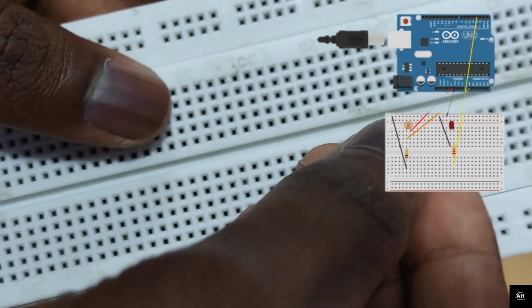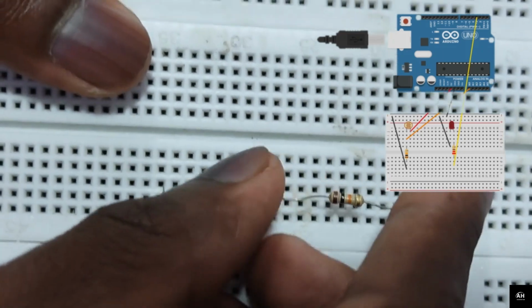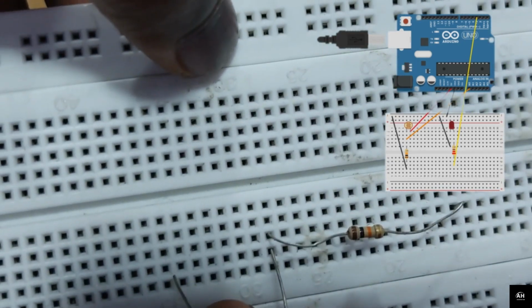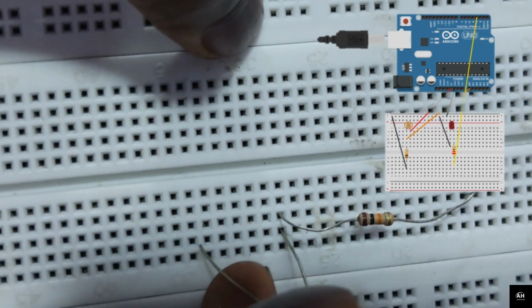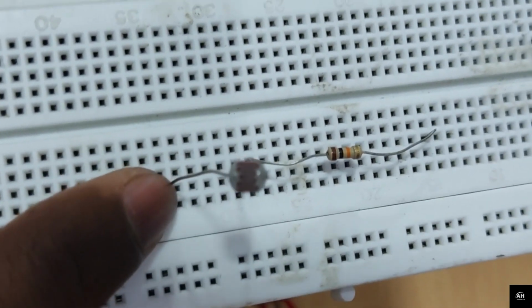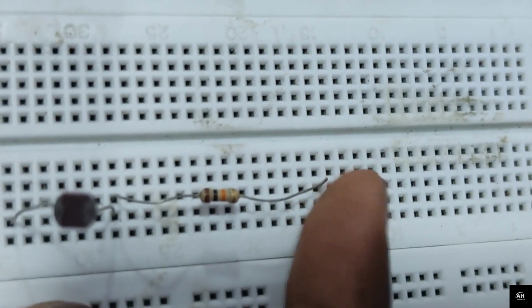I will insert the resistor on the breadboard and connect it in this format. You can see here I have connected it in this format, and we will connect our LDR sensor with it. It will be connected to the same input as the resistor, so they both connect with each other. Using the middle intersection of these two pins, we will get the analog output, and this end of the LDR sensor will go into the 5 volts. The 5 volt will be connected here, and the resistor will be connected to the ground pin.